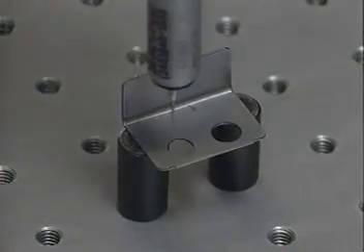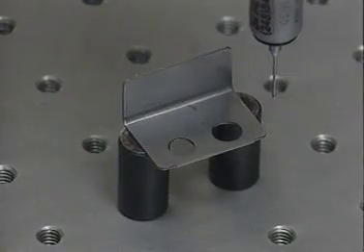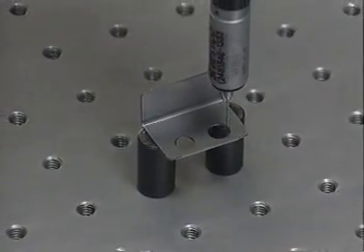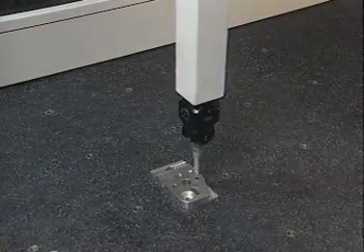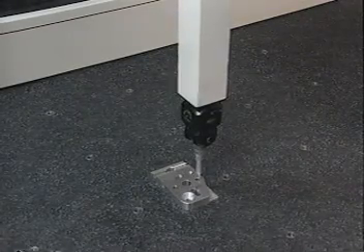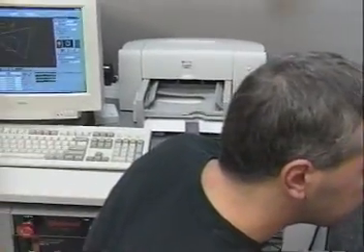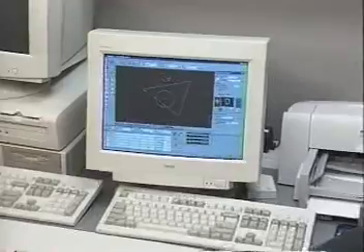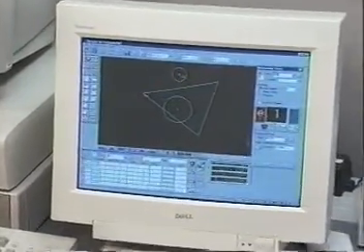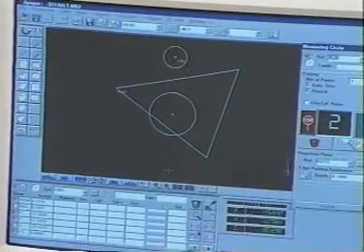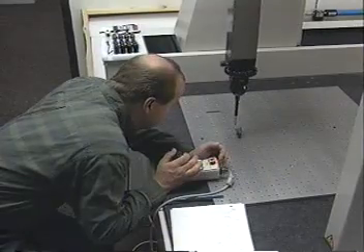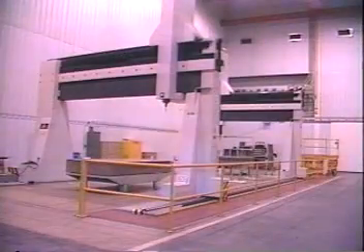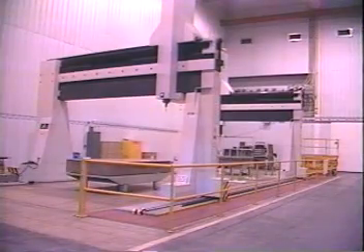Probes are primarily electronic and use a ruby or sometimes ceramic tip to contact the part. Probes can also be non-contact in nature. Reader heads, traveling on each coordinate axis along built-in measuring scales, transfer data on the machine's position from the probe to the computer interface. This dimensional and geometric data is then calculated, compared, evaluated, and recorded. CMMs are available in a variety of styles and sizes, ranging up to systems that are used to inspect large aircraft components.